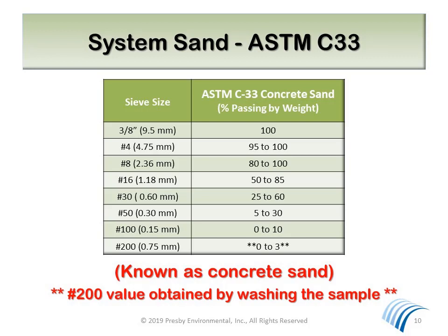It also provides enough void space between the sand particles to allow oxygen to be distributed around the pipe, which helps to maintain the aerobic environment critical to the desired bacterial processes. One final note: because small amounts of silt and clay can have a dramatic influence on the sand's ability to function properly, it is limited to 3%. This is shown as the material passing the number 200 sieve.